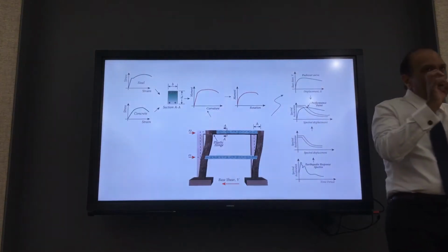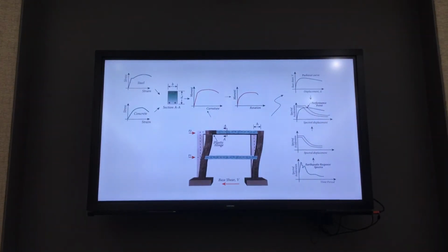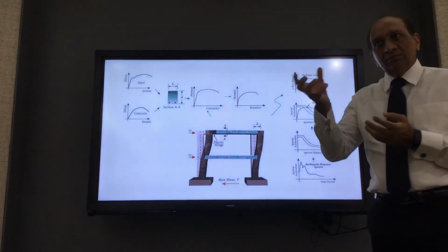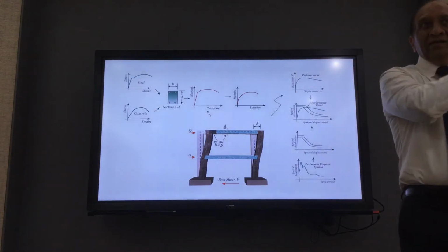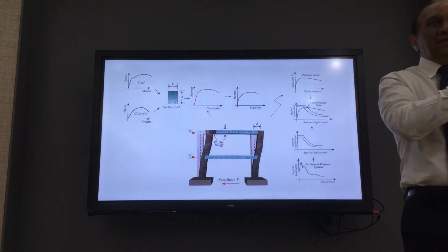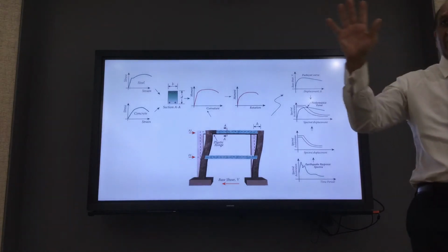So we multiply this moment curvature curve by the hinge length, and we get the moment rotation curve. So now we get a relationship between bending moment and rotation. Now if you remember, in Dr. Panchit's class, he told you about the relationship between rotations and moments, right? From the analysis point of view, that means there is a matrix that relates the actions with deformations.